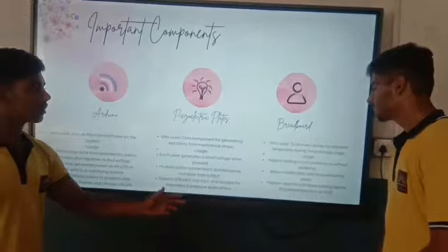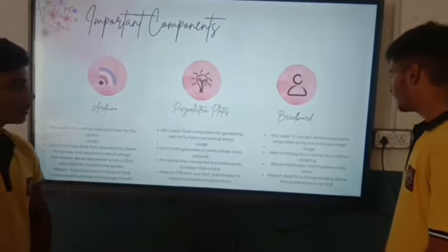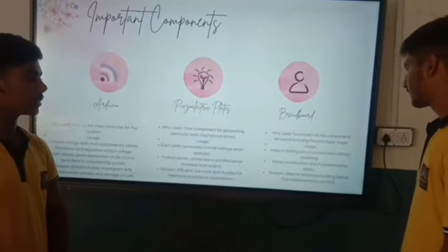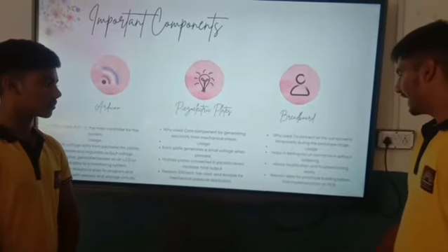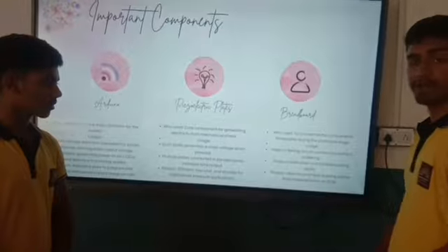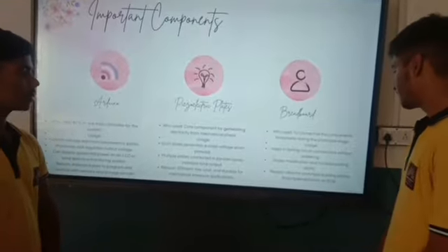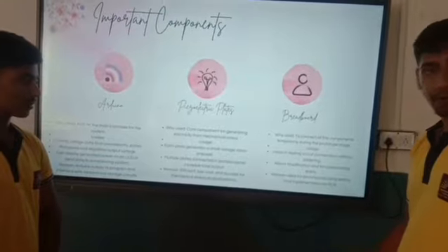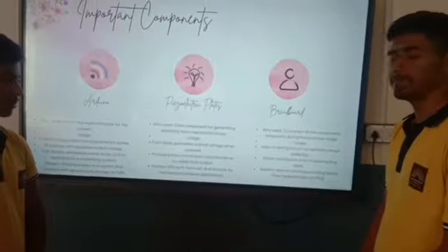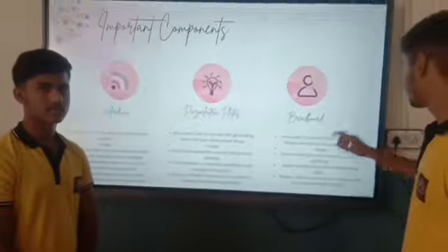Another component, breadboard. Why used? To connect all the components temporarily during the prototype stage. Usage: helps in testing circuit connections without soldering, and allows modification and troubleshooting easily. Reason: ideal for prototype building before final implementation on PCB.